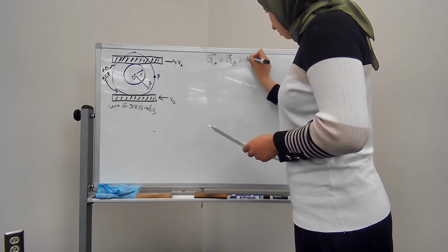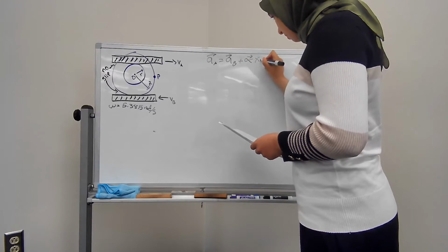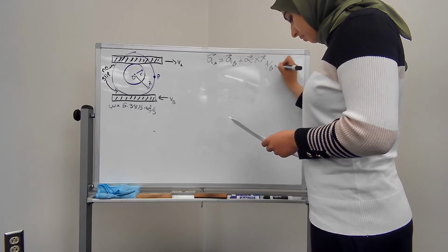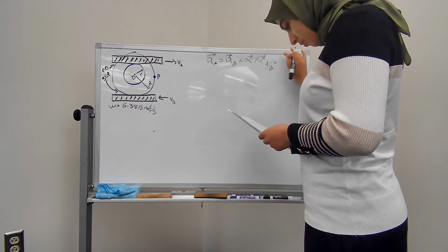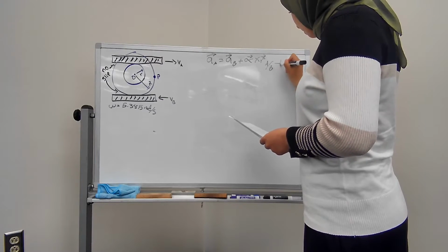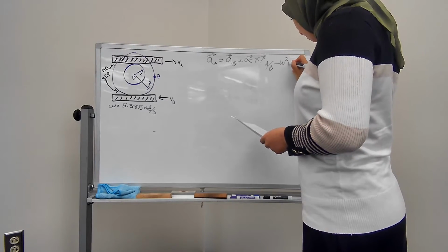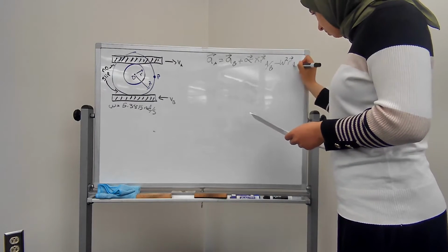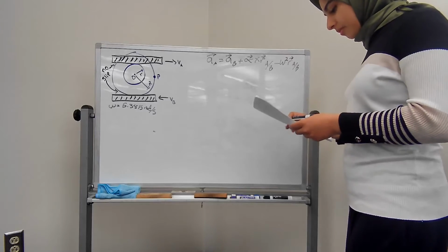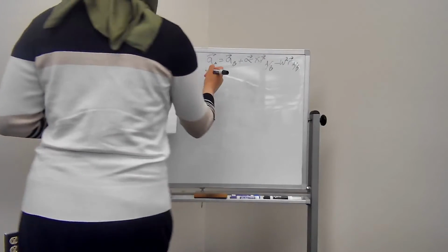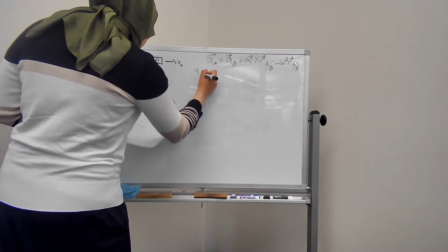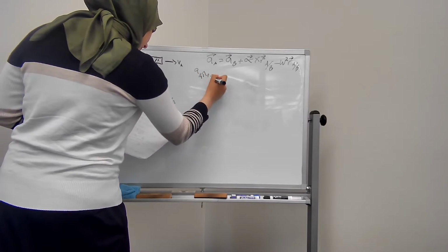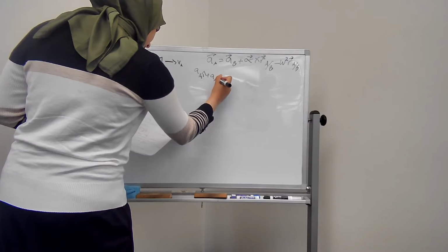As we work through this equation, it is important to break up the acceleration into each of its components, meaning in the i and the j direction. So for this equation, we'll end up with A of A in the i direction plus the acceleration of A in the j direction equals the acceleration at B in the i direction plus the acceleration at B in the j direction plus alpha cross R of A slash B minus omega squared times R of A slash B.